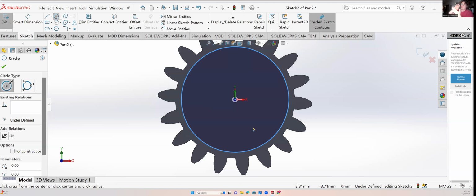Basically, the first gear, the crank, is going to go almost directly on the surface of our fixture. Okay. And then we're going to have that attached to the compound gear. So the pinion of the compound gear is going to be meshed with the large gear on the crank. Okay. So then the large part of the compound gear is going to interface with the fan gear. Okay. But that larger gear is going to be 6 millimeters off of the surface of our fixture. Okay, so basically on this gear, I need to make a little spacer profile.